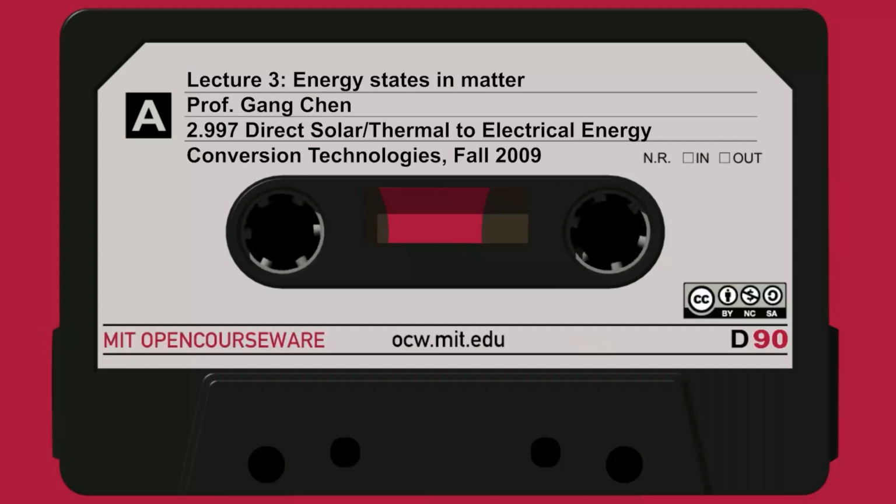If you look at gallium arsenide solar cells, people use thin films because they absorb well. In silicon, it's very hard to use thin films because they don't absorb. So as a compromise you make the cell thicker to give that chance to happen.